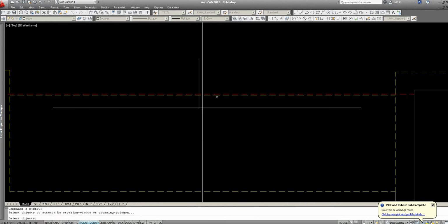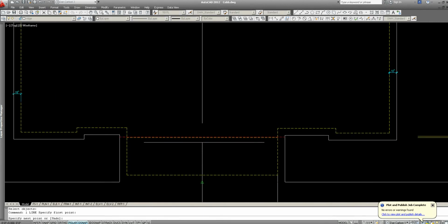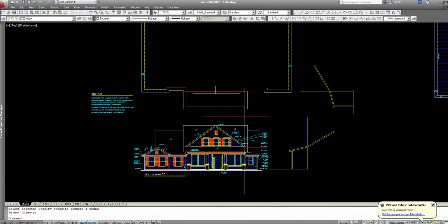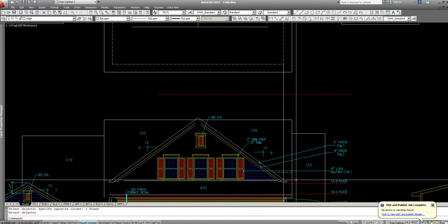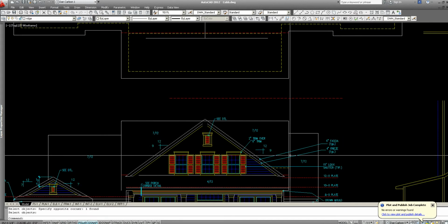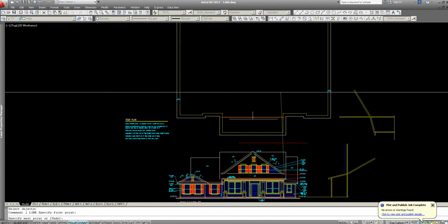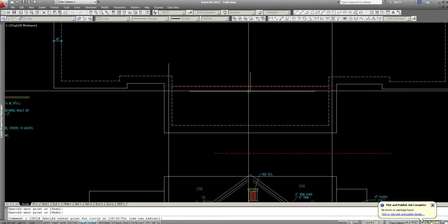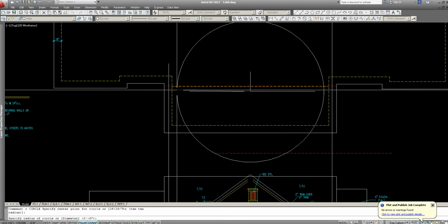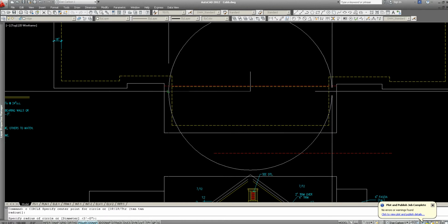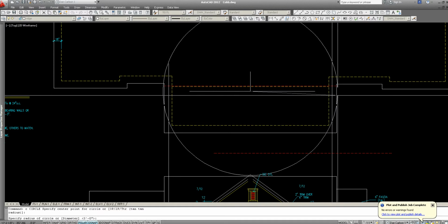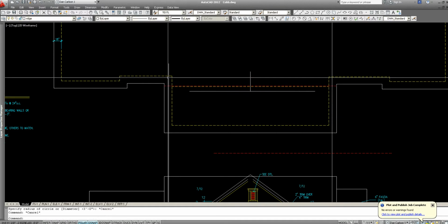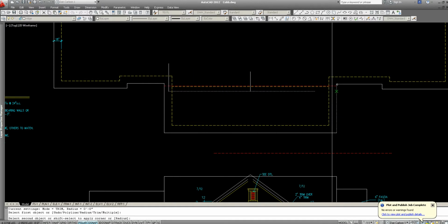Okay, so this is actually going to be here. And that should be in the center of this line, by the way. There, see how that's in the center? Alright, so let's try that again then. This is here. This is here. And I always do circles to see if I'm actually centered. I do a circle and just stop where my cursor hits, and I make sure the other side also hits, and you can see it does. This side and this side match. So I know I'm centered. And then I just fillet this here and here. And then I erase these because these lines don't actually exist.